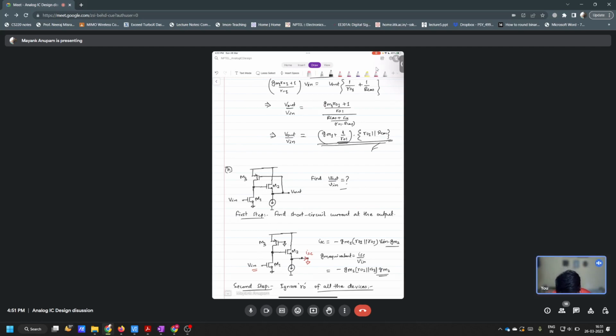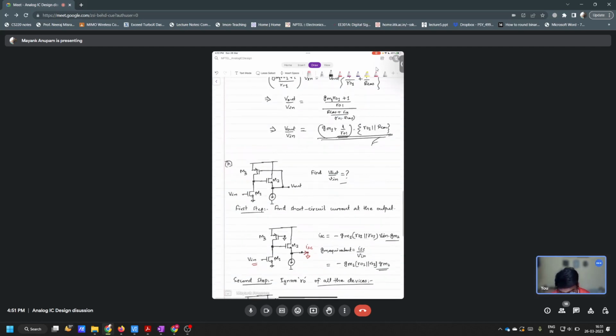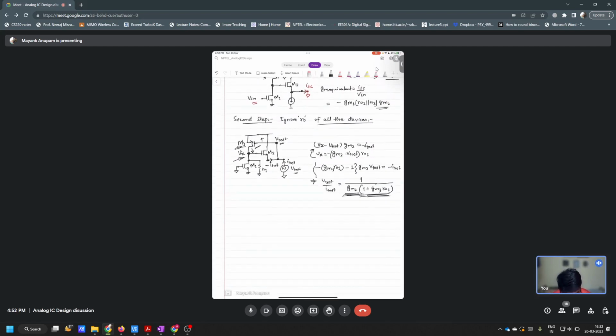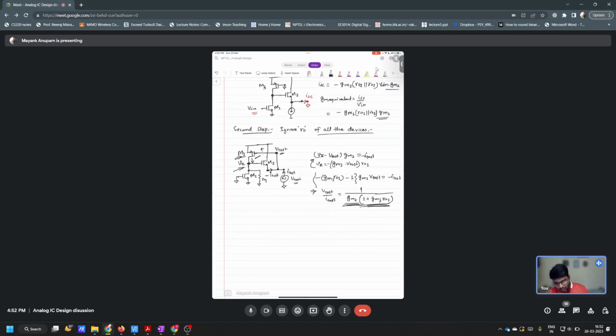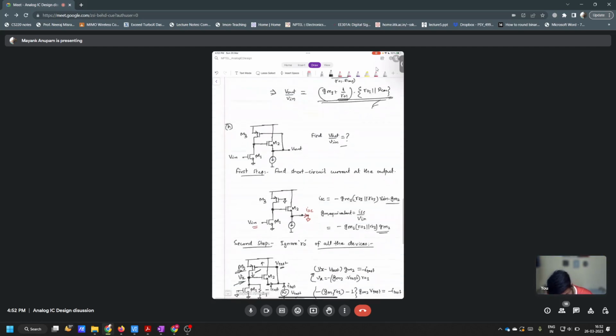Now, can you tell me another way to look at it? From the perspective of R out only. Yes, you were right actually. The R out, it is a way to reduce the output resistance. When you put it in feedback, you have simply reduced the output resistance, and that is why it becomes a very good voltage source, a voltage controlled voltage source, isn't it? Yes. Fine, nice.